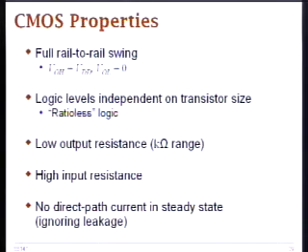And what this does is basically make it really immune to noise sources, because it provides a good solid voltage, as we discussed last week. That's a very important property when you have large noise margins. It has very high input resistance. It's also very important because that means it doesn't load the previous gate much, except in the transient regime where there is a lot of capacitive loading.